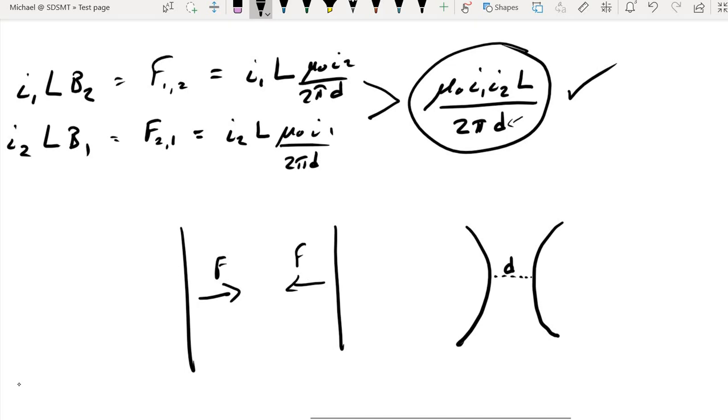One of the wires might get ripped out of its connection points, or one of the wires might sever. A third option is that the wires might actually come into physical contact. So those forces continue pulling and the two wires actually touch, and hopefully the wires have some kind of insulative sheathing on it. Otherwise you could end up with some kind of a short circuit event.